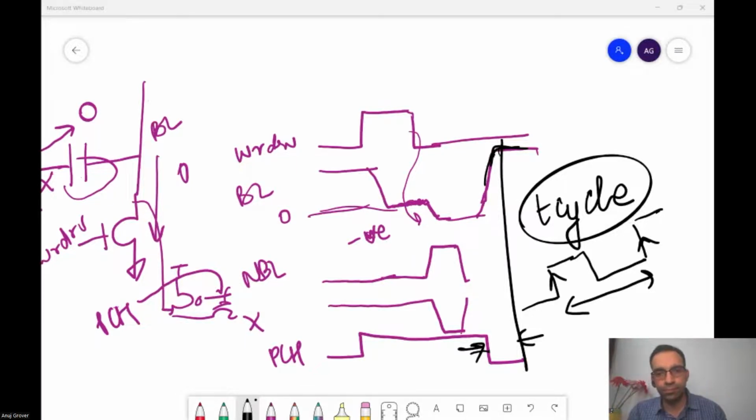Okay, so in that IO circuit part, it is mentioned that BL charge discharge time of 100 picosecond. So this is the T cycle time of 100 picosecond. No, this is not the T cycle time. This is the pre-charge time. T cycle time is from the first rising edge of clock to the next rising edge of clock, which means it includes word line selection and all those delays. Okay, got it.